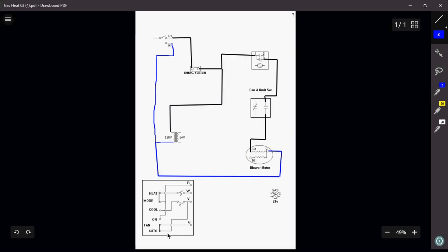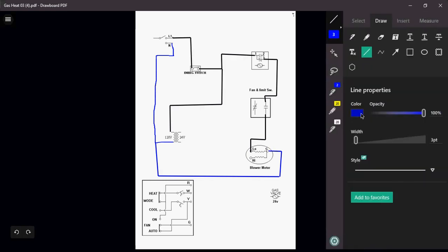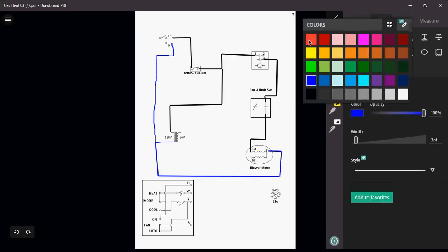I have a gas valve and a thermostat. So what do I do to complete my circuit and make this work the way I want? Well, we're going to now focus on the 24 volt side. We have pretty much completed the line voltage side of our circuit so far.